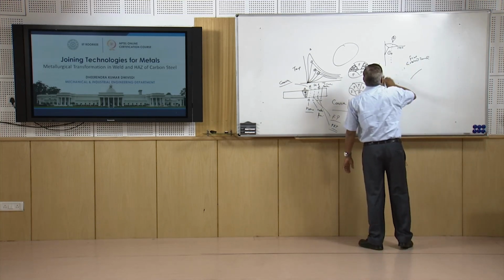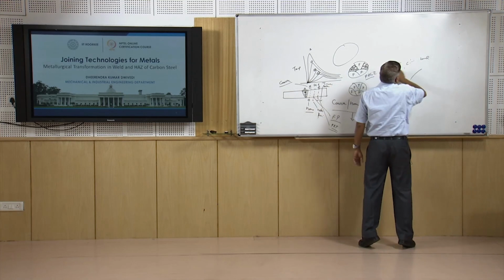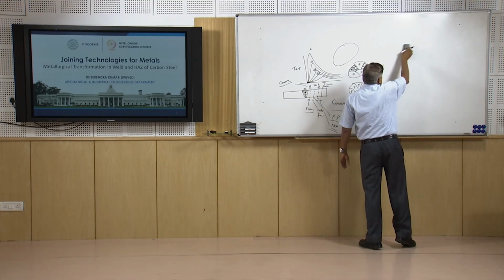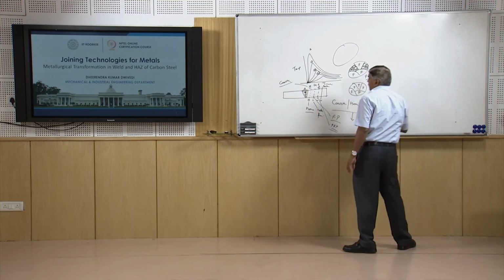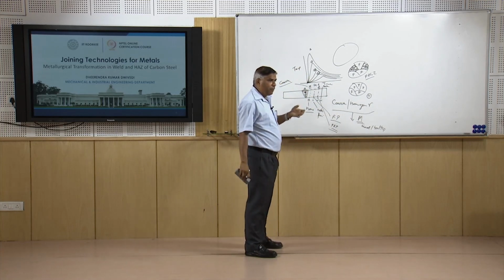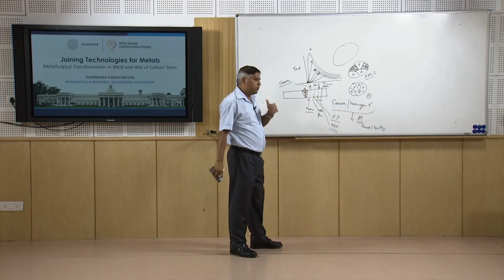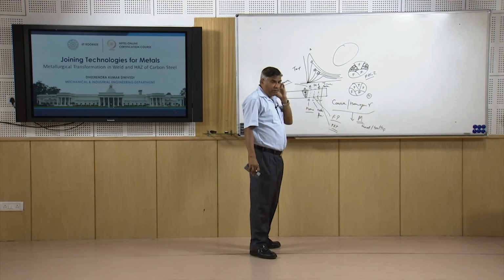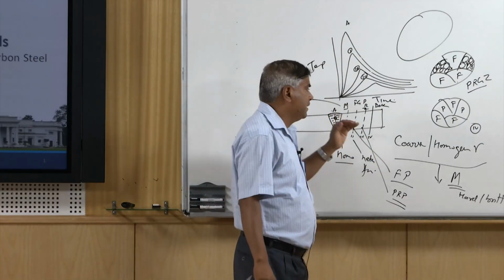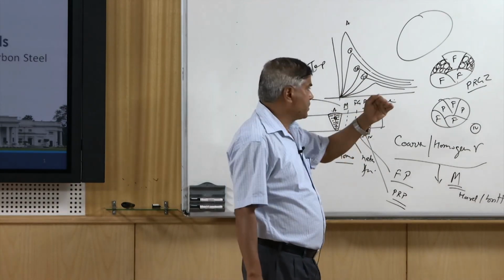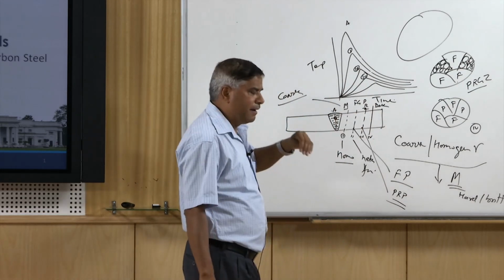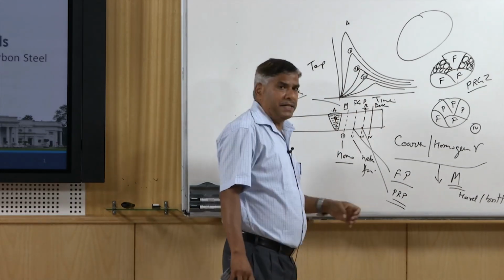Further, if very heterogeneous austenite is formed, where due to the lack of time the pearlite, which is of higher carbon content, and during the subsequent cooling phase of the welding, high carbon austenite formed as a result of the transformation from pearlite to the austenite. So, this will be resulting in the high carbon martensite also.